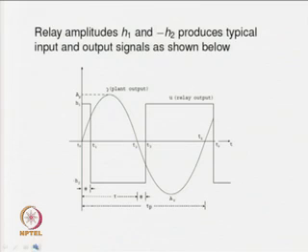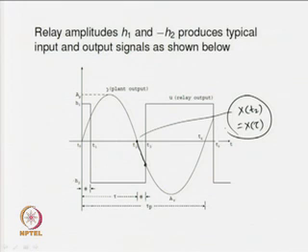Similarly, we will target the other span now, the output starting from time t equal to t2 and going up to time t equal to t3. What is the time span here? It is nothing but θ seconds only. So, the output will be obtained for θ seconds only, but it is starting at time t equal to t2. So, one needs to find the expression for x(t2), which is nothing but x(τ), because this will act as the initial condition for the solution of the state equation.